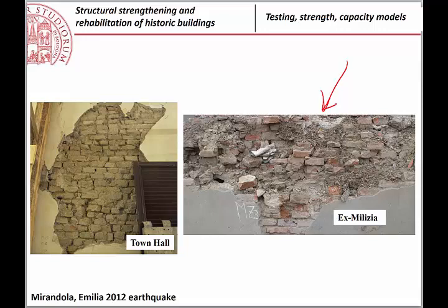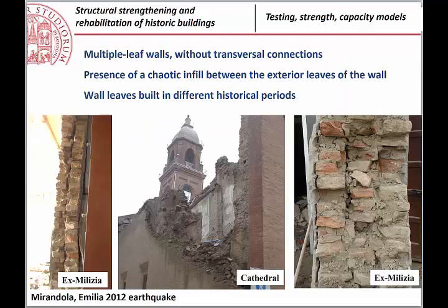And when you use clay bricks and you must realize big walls, how to organize them is not so simple. They must be all of the same size, of course, and then they must be organized in a given way in order to have a good quality of the masonry. If you don't do that, you get something like what you see here.